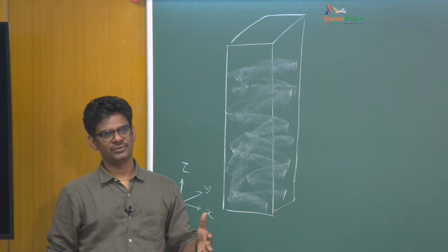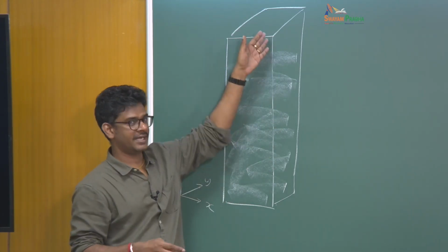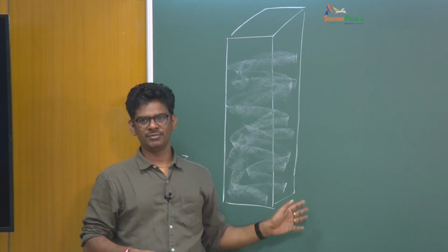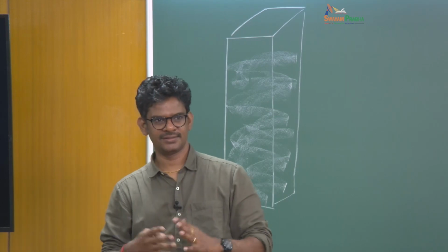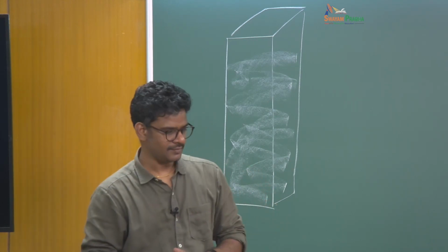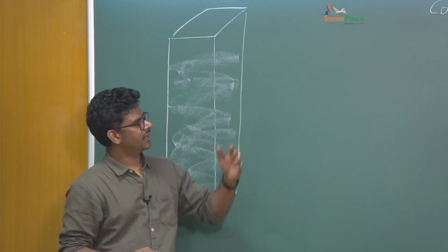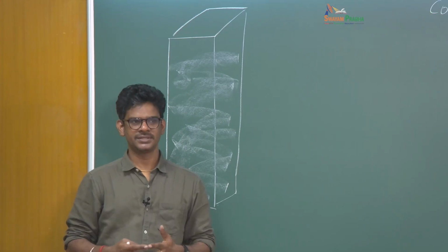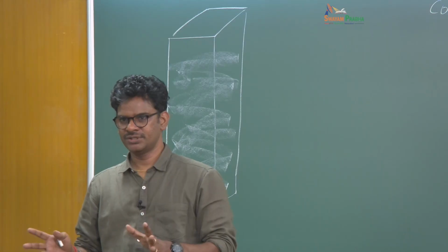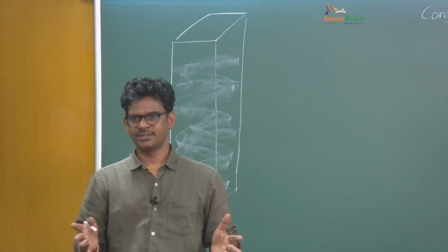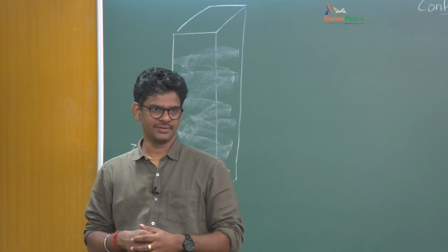You will get an equilibrium distribution based on a certain profile. So our task here is to look at the problem of a Brownian particle in a gravitational field. What is the equilibrium distribution of the particles? This is directly applicable to chemical engineering, as I said, sedimentation, floating, etc. This problem we again want to approach from the continuous Markov process point of view, in other words, the Fokker-Planck formulation. We know the structure of the Fokker-Planck equation. We just need to find what the characteristic functions are, what is the drift A, the diffusion term B, and so on.